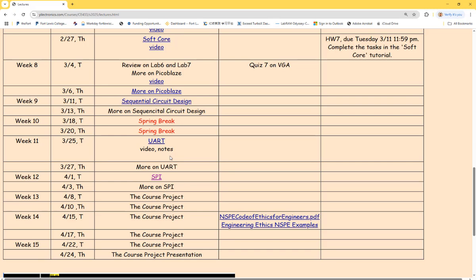I2C is a lot slower than SPI. That is why we don't want to use I2C for SD cards. So SPI is usually used for SD cards. And what about I2C though? I mean, what's the benefit of I2C compared to SPI? They have a lot of sensors, right? Yeah, all the sensors have addresses. What else?